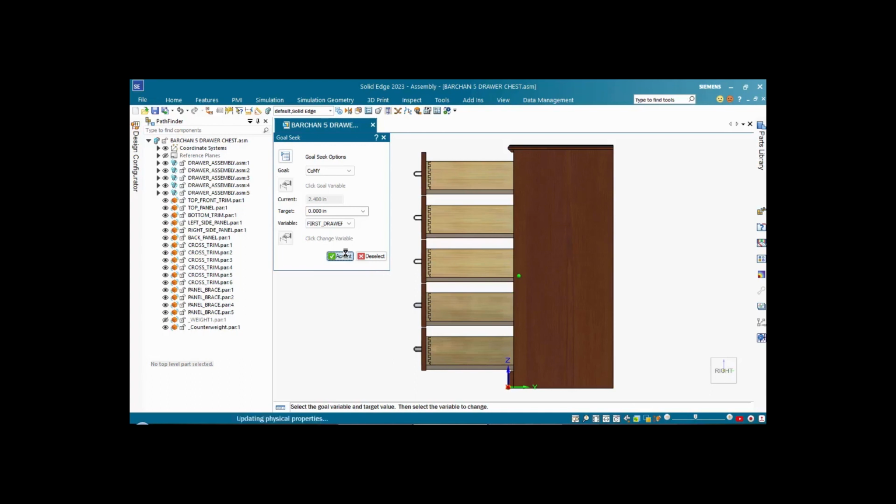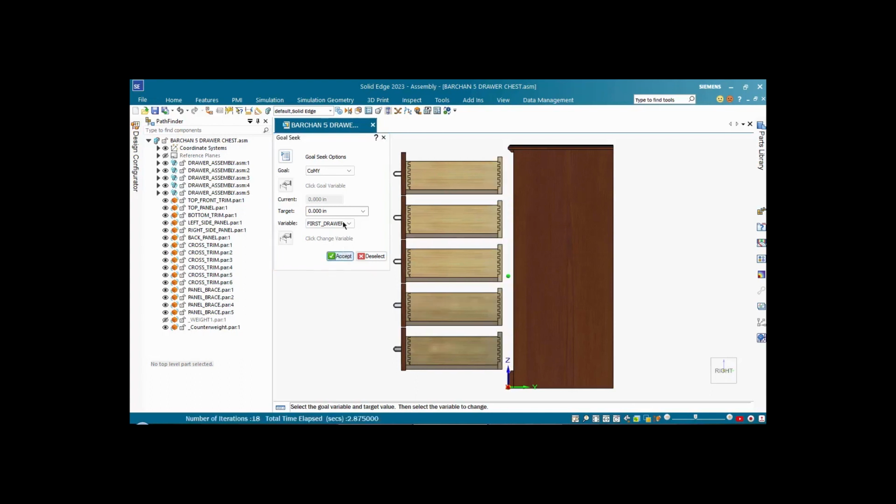the system will go and calculate the position of all drawers. And as you can see, they can be completely pulled out before the dresser starts tipping over, even in this unrealistic situation where they're completely pulled out. This is good information, but what if somebody is leaning on this dresser? To test for that, we need to add additional load on the top drawer.